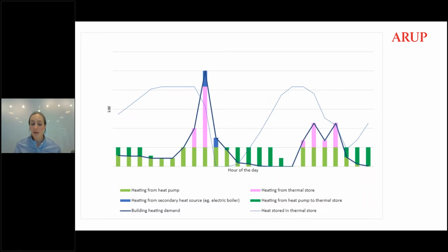And this is something that often needs to be brought into the design early because it can be quite large and particularly tall, where you're looking at maximizing the efficiency of the thermal storage and stratification. So this was something I wanted to highlight, and which we've given a bit of emphasis to in the document, because it is specific to heat pump installations in particular.